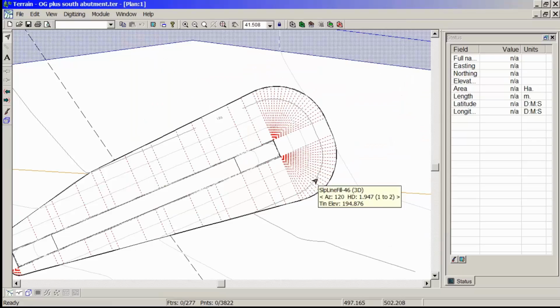Okay, a little recap of what we've done so far. Just after the north abutment that I did, I have opened up the original ground again as a background, brought in a ballast feature or a ballast wall, created a fill, moved the ballast wall around to the correct location, rotated it around, changed its elevation, created an engineered fill at the bottom of the ballast wall to riprap, so it's a little bit more stable.